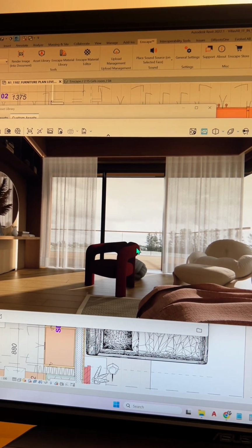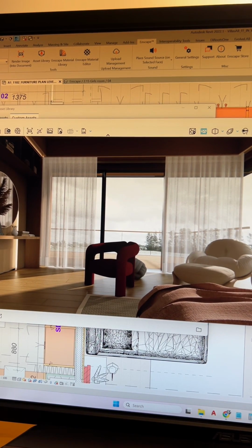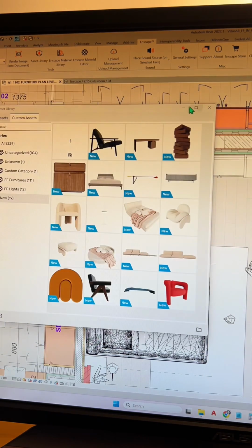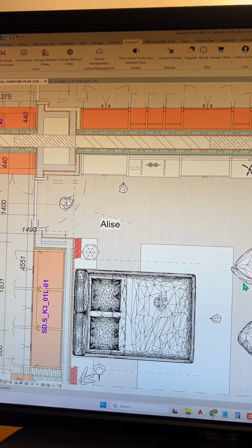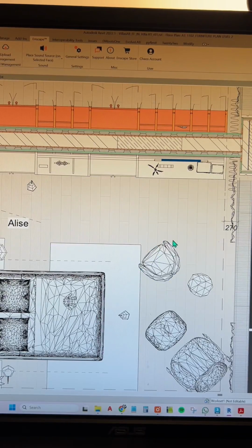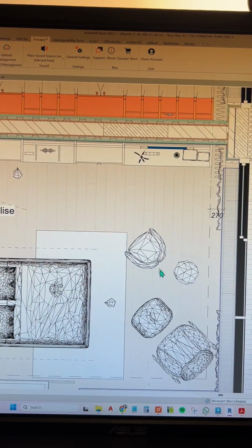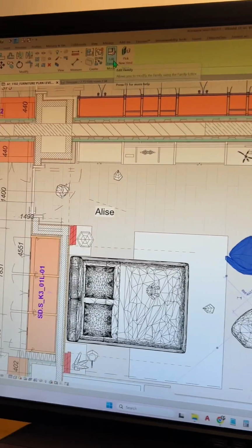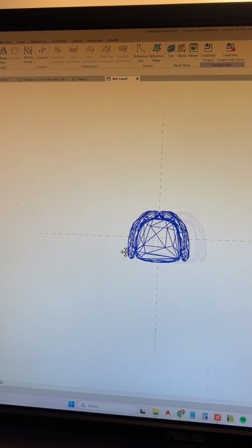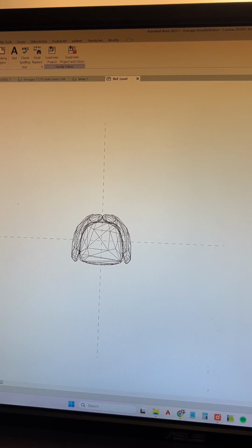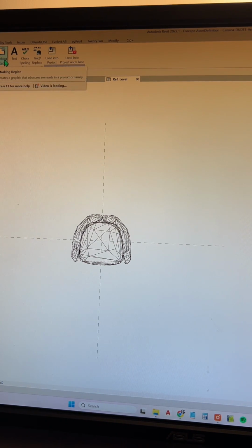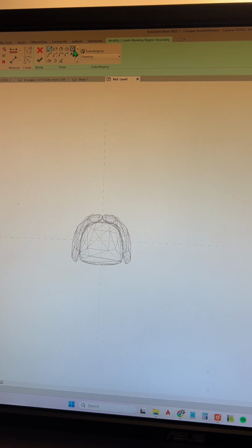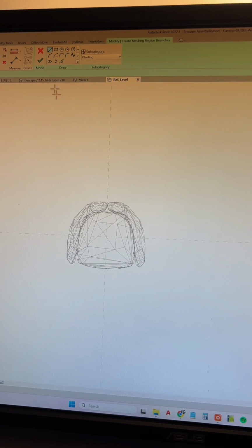The other thing I love to do when I have to submit the floor plan to the client is this: I would not submit the floor plan with these triangle-looking furnitures. So I click on this furniture, click on edit family, and I usually redraw it into the shape of the chair using the annotate tool. This is something you can do just once, and then you can copy these assets from file to file, and you will always have good-looking furniture. This is the trick I'm doing.